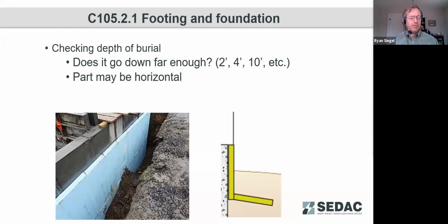So we have run into instances, particularly for perhaps a renovation, where trying to dig down 2 foot all the way around a foundation can be very difficult. But what may be much easier to do is to dig down 12 inches wide and 12 inches deep. So that would allow me to get 1 foot vertical plus 1 foot horizontal to give me my 2 foot of depth and 2 foot of distance without having to dig down the full 2 feet. So there are some practical benefits to enabling this horizontal.